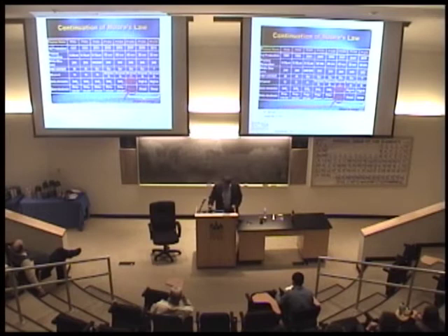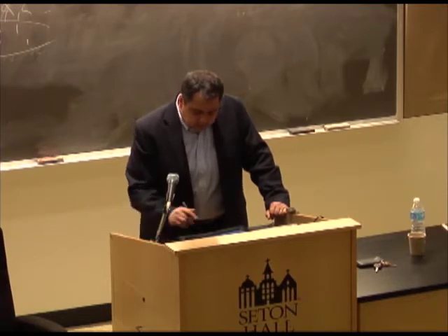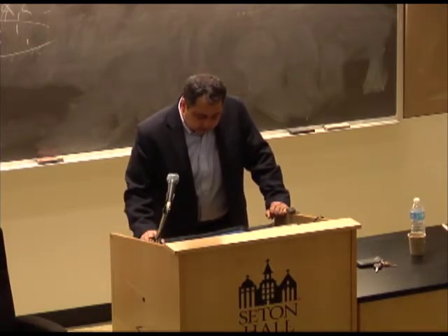And this is the breakthrough that I was talking about. So you see that silicon dioxide, and at this point there was a suggestion, and this is the 2005 roadmap. In 2005, there was the projection that it's going to be high K, and this really happened. December of 2007 or 2008, I think 2007, the gate has been changed to metal, okay?